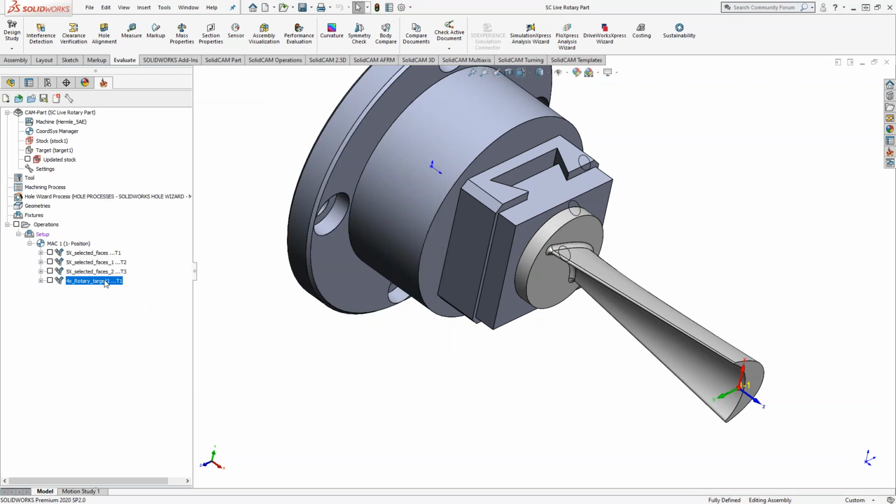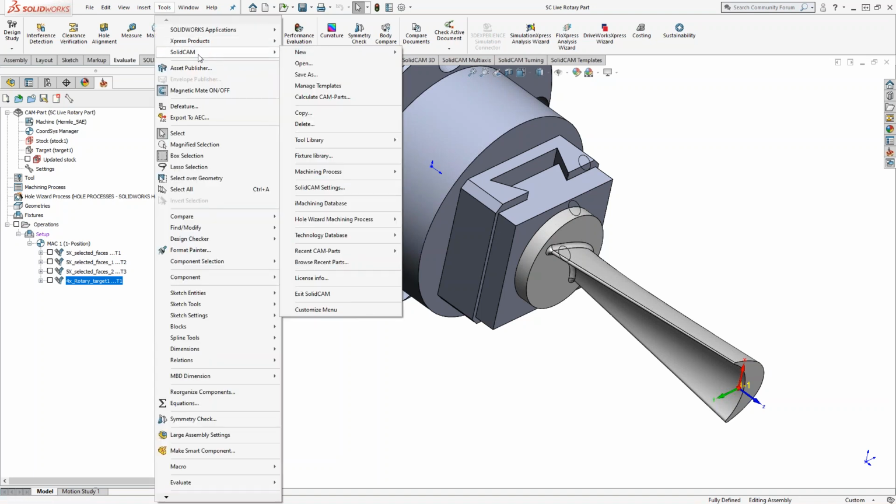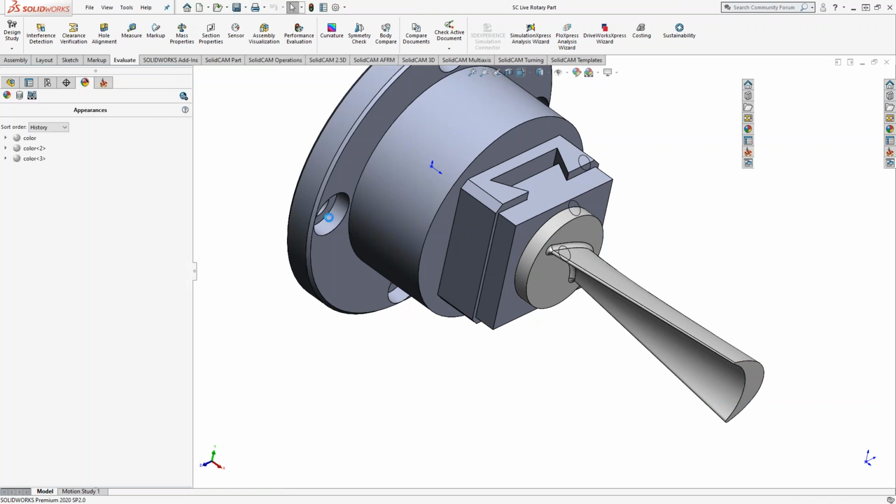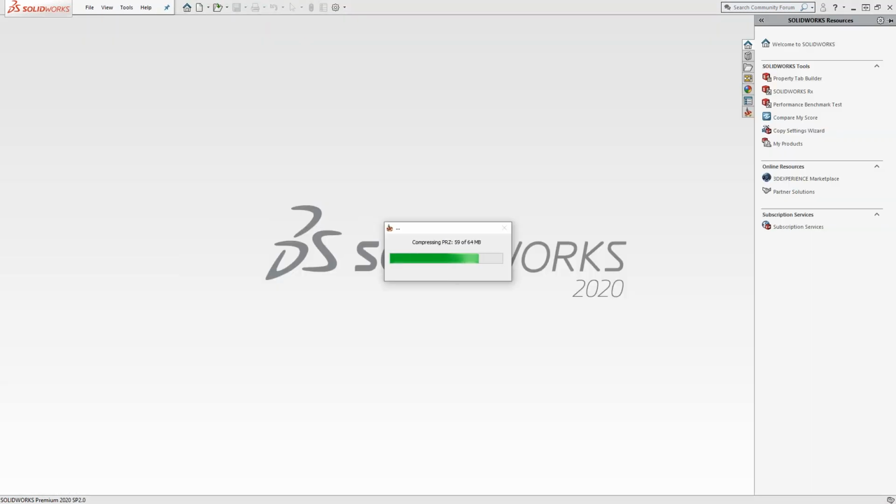All these other toolpaths we talked about today do the same thing, but with bare bones. They're basically just limited parameters. They're looking at a specific thing. So the rotating 4th-axis toolpath is doing almost like a cam follower style toolpath. The Swarf cut is literally just using the side of the tool to cut a blade, or like Kevin said, trim some plastic. There's a lot of different toolpaths in here, but the discussion is basically like we talked about with profile and pocket. You're really just trying to figure out which one is the less clicks, which one matches what it is you're trying to do with your part.